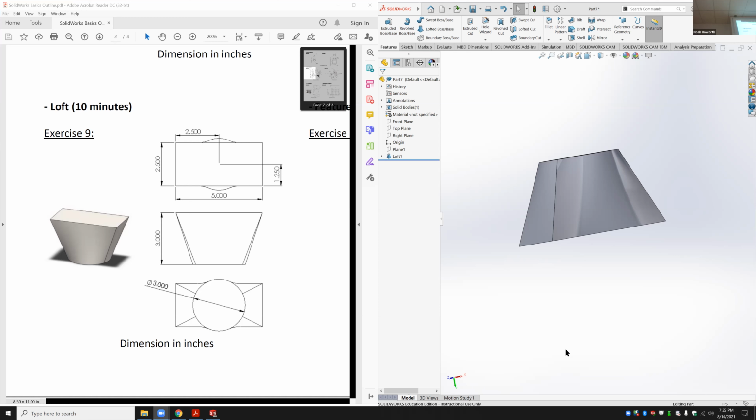Make your plane. So go to Features, then Reference Geometry, and then Plane. Okay. And drop down whatever plane you have your sketch on. So drop down from right here, click that black triangle. Black triangle right there. To the right, not that one, keep going to the right. Just to the left. Oh, there.